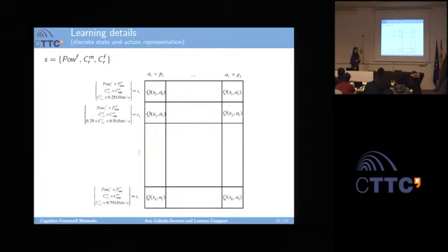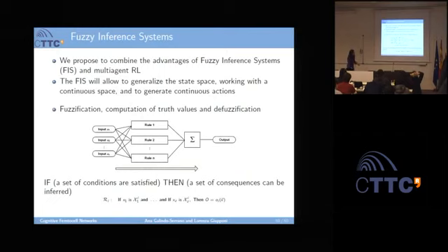And the same for the actions. For our case, we use 60 power levels, which is a lot, and that is why we also have such a long learning period. But if we could represent this somehow in continuous form, we would for sure have better performance, because we would know the real state, and we would be able to take the more accurate action for the given state. So we have 3 steps. We need to do a fuzzification process, compute some true values, and then defuzzify these true values.